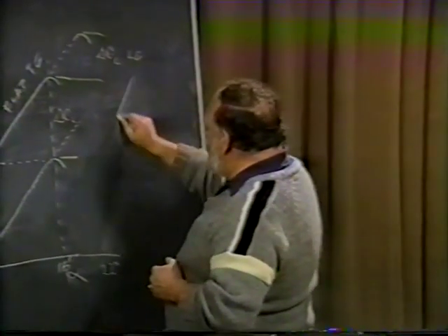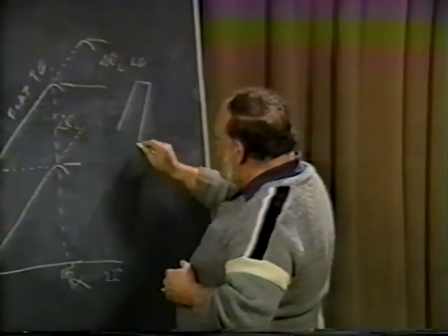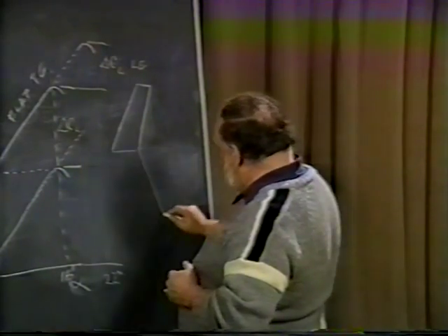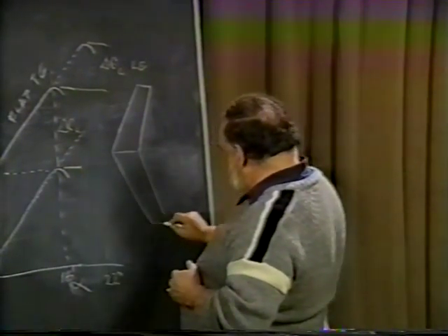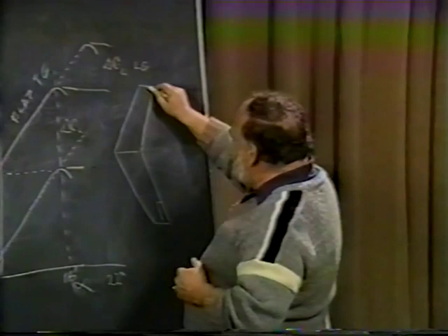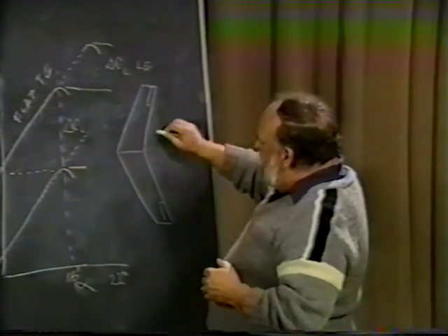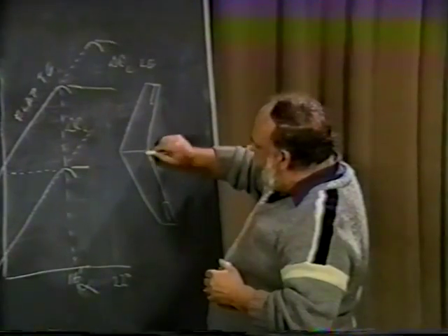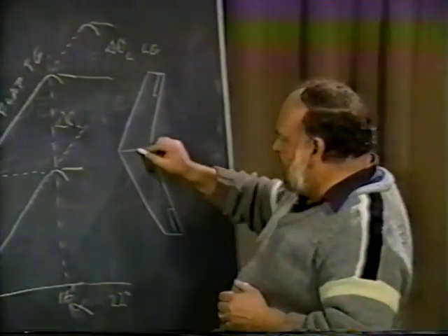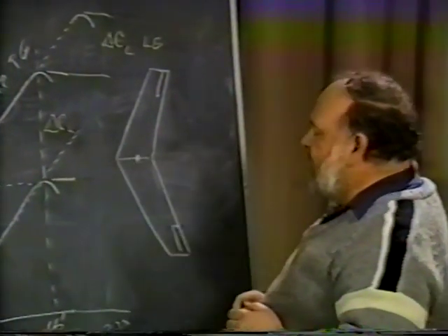Let's draw the flying wing from a top view. It was swept back, with the outboard sections here becoming ailerons and roll control. And they used the flaps in this inboard region here, and it was somewhat forward already, with the center of gravity probably being located here.